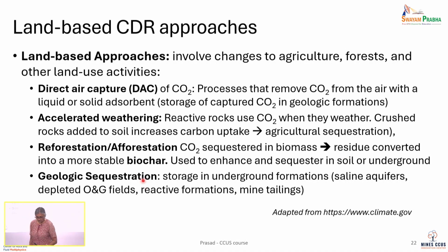When we look at geologic sequestration, we are examining formations where we can store at least about 1 kilometer into the subsurface, often more. The reason we want to go deeper is that there is a sweet spot, because as you go deeper you have higher pressure, and so you cannot make use of the pressure differential as much. If you're too shallow, you're very close to the water table. So we want to be deep, but we don't want to be too deep.